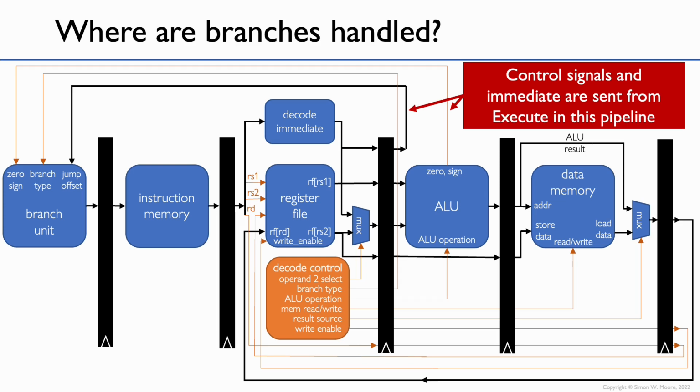And the simple thing will be that the branch unit will have just kept issuing program counter values to fetch the next instruction, and as a consequence we will have an instruction being fetched and an instruction being decoded that are likely to be the instructions after the branch, and in other words they would have been fetched in error. So let's look at that in some more detail.